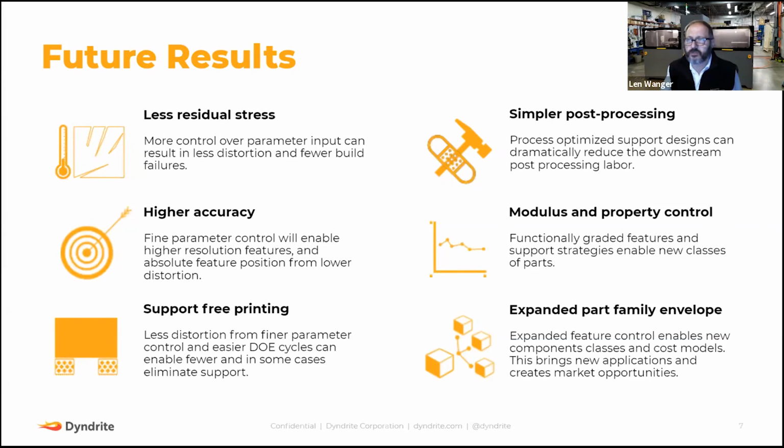And again, I'll try to use an analogy here. If you were to take a box of tissue paper and you were to press down on it, the tissue paper squishes together. When you let go, it releases. And there's a spring force that is trying to push back on that compression. We have a similar thing with our fabric. When we compress it down, it wants to expand out again. So you have a spring force acting against it. And that acts as a residual stress.